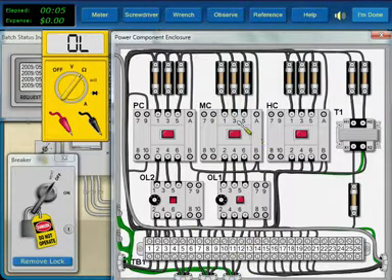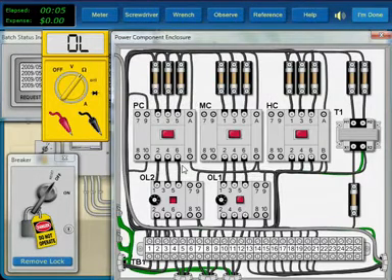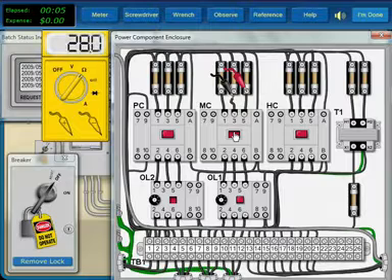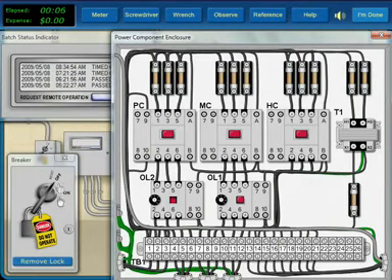We begin to disconnect the wire, but find a loose terminal. Since this fits the symptoms, we tighten the terminal to repair the circuit. To verify the repairs, we test the full path through the motor. The low resistance reading indicates the path is complete. Next, we get ready to test operate the system to make sure there are no other problems.